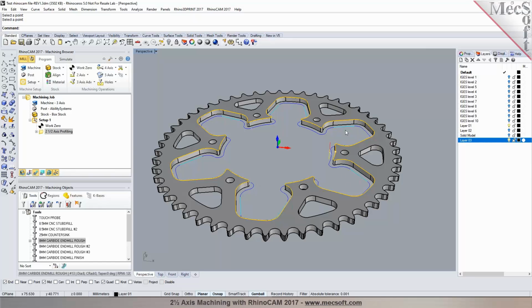So we could do what is called a sorting, and we can specify a sequence for the sort. So we don't really have to have it chained, but you can specify it to sort them, so go from one pocket area to the next area. Or you can automatically have it do based on the order in which you select them. If you don't want it to sort it, you can pick the sequence in which you want it to cut.